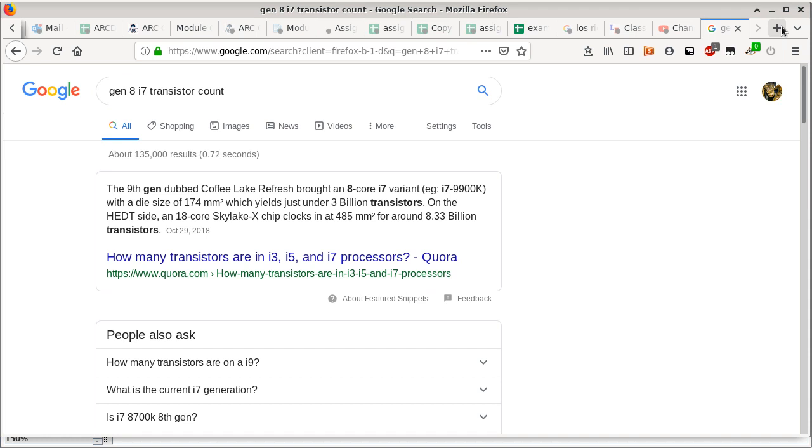Like the etching process is chemical based. So depending on how the solution gets circulated, and also the temperature distribution during that process, different parts of the same wafer can experience a different rate of getting etched.